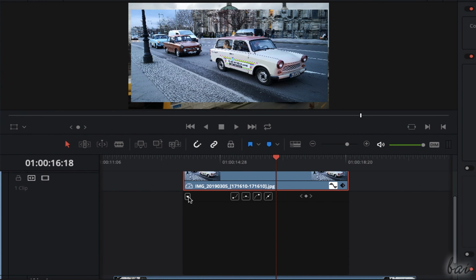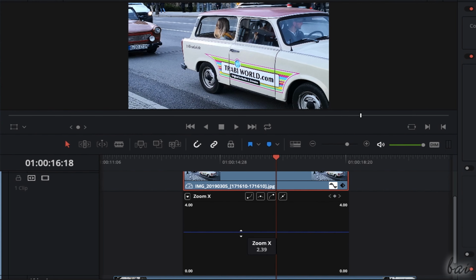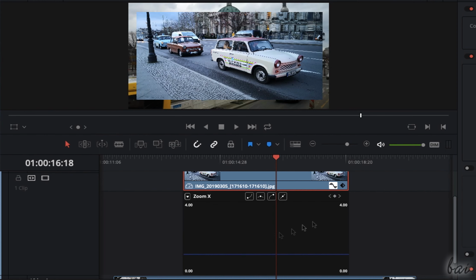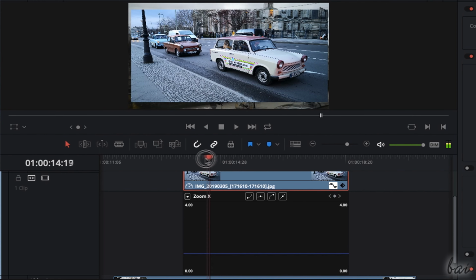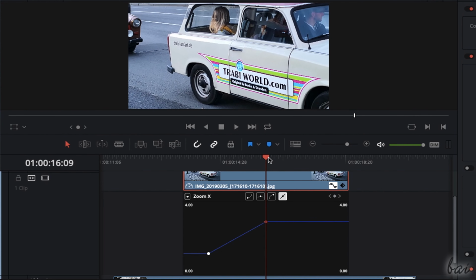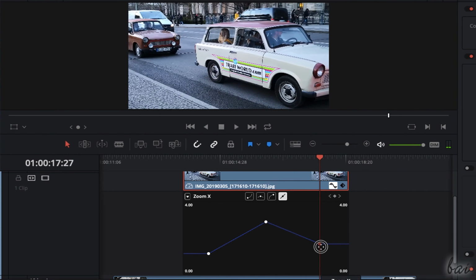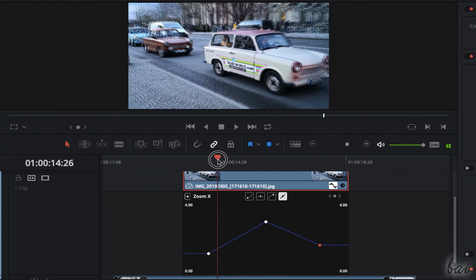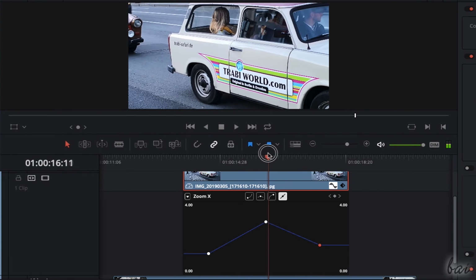Select the clip property from the list in the top left corner. At first, this is constant in time, showing a flat line on the graph. If you place the red marker in time and use the rhombus button above, you create a marker called keyframe, saving the current property value in the instant of time it is placed. In this way, if you place 2 or more keyframes in time saving different values, you create an envelope curve that changes the property during time.